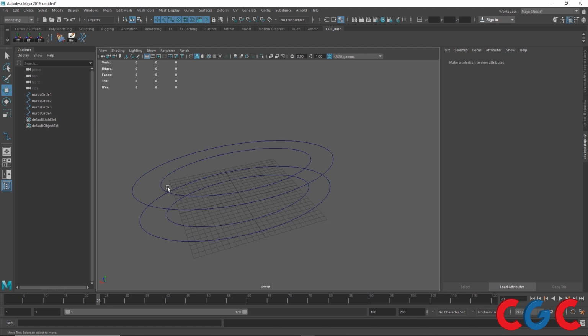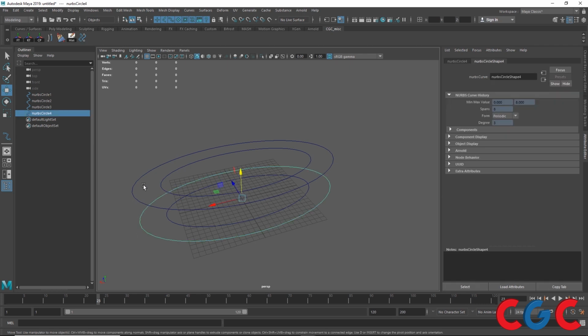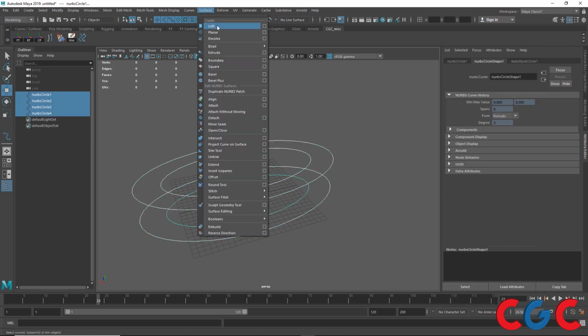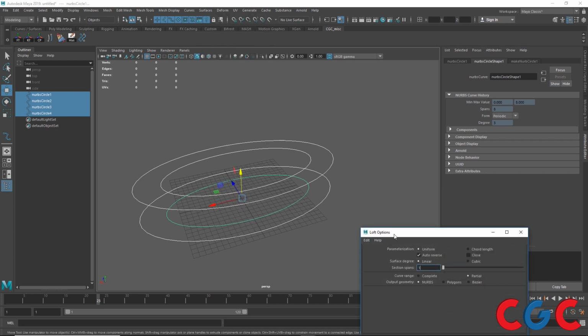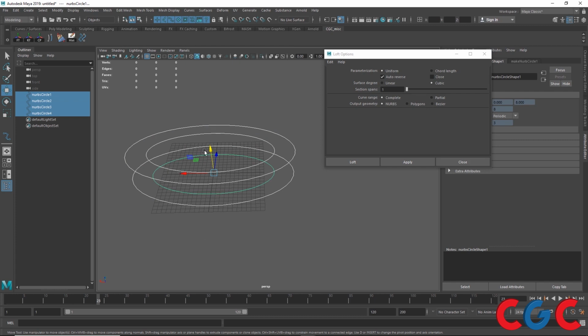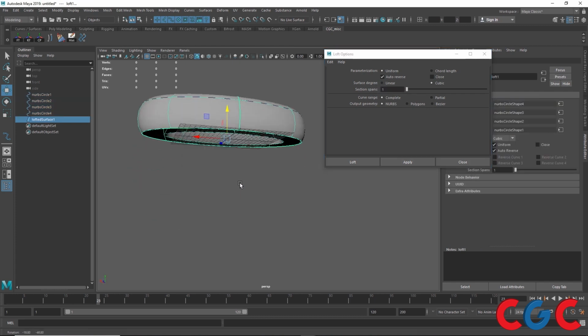I'm going to create a thick surface. So something is going to have some volume, something is going to be thick, not a plain surface, right? So for example, here I want to create something like a cylinder using this with this as the thickness. So I'm going to select them in order one by one. I'll go to Surface, Loft, under the Loft, Edit, Reset Settings. I'm selecting them by order, apply, getting a result.